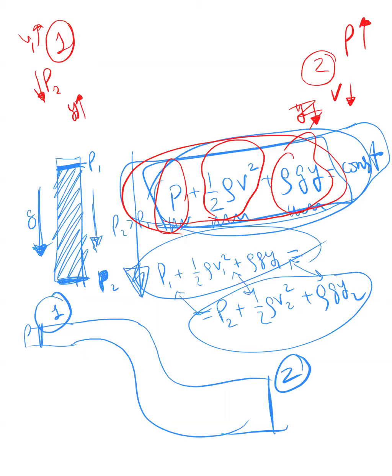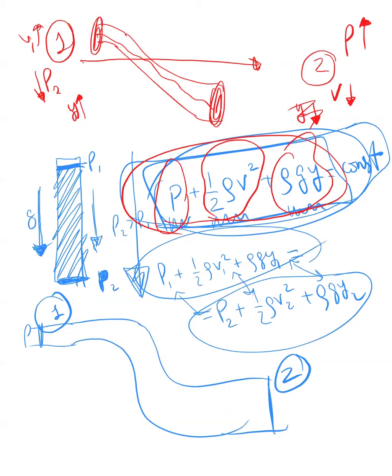So in the first case, if your velocity dropped, that kind of makes sense. You're moving from low pressure to high pressure, and this high pressure is slowing you down. Or if you have a pipe that goes from a higher elevation to a lower elevation, that also makes sense. You're moving down, and because of that, there is effect from gravity, and you have more pressure here compared to there. And of course, both of these things could be happening simultaneously. You could be at the same time moving from a higher position to a lower position, and your velocity could be dropping at the same time.